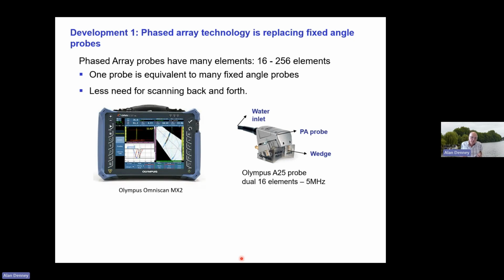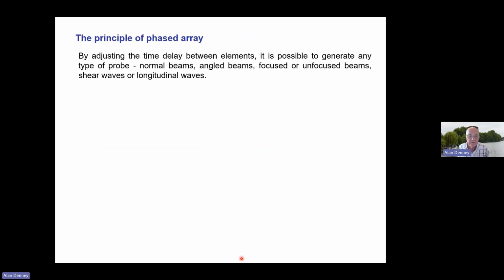That's a UT setup for phased array, and it's showing this wide beam, which is an accumulation of many signals from many channels and probes, which gives you a live view of the indications, a simulated view. So what's the advantage of this? Another advantage of this modern technology is that it gives you full recording of the scans and images, so you can go back and reinterpret or look very carefully at the interpretation of what you've got.